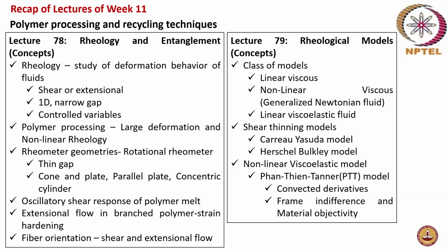Lecture 79 was on rheological models. Different classes of models were discussed, like linear viscous models and non-linear viscous models, which is nothing but the generalized Newtonian fluid model. And then the linear viscoelastic fluid model. This was followed by shear thinning models, where two major models, the Carreau-Yasuda model and the Herschel-Bulkley model, were discussed.